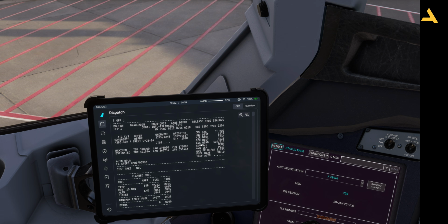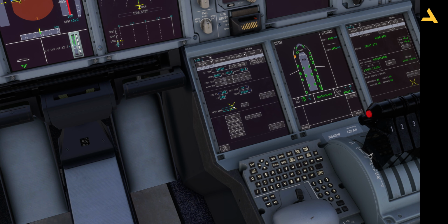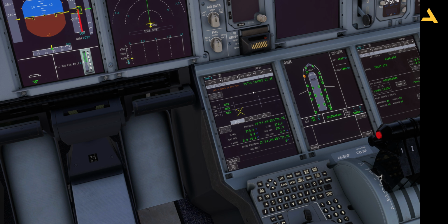So over here you can see this average wind is shown. This is the average wind's direction, and you can see the speed of the wind. So it is 10 knots. So I can just go and enter 10 over here. If you are flying the Airbus 350, then it automatically picks up the wind information. But right now, this wind is not available. And then you can see the IRS alignment is now complete. For IRS 1, 2, and 3, you can see the position is there, and that's it. So accuracy is also there.